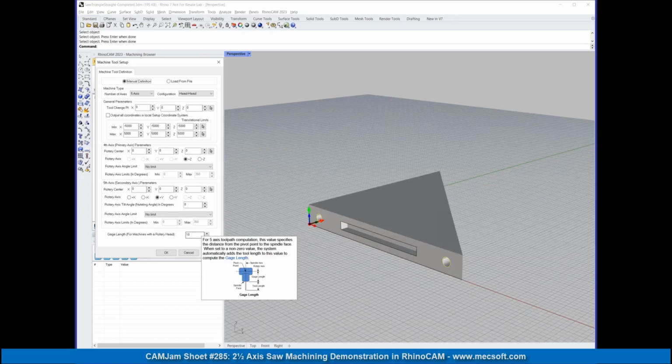Yeah, and I'm wondering how we zero out our tool, because we have a tool sensor, like a touch-off probe sensor thing for all the other tools, but not for the aggregate head. Yeah, so it might work if you had it pointed straight down. So you'll point it straight down, and then you'll zero it out, and then you'll figure out the height, right? Height of which is basically the height from the touch-off point to your spindle face.